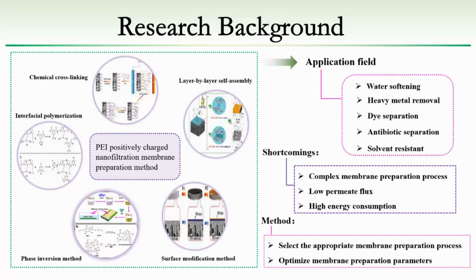However, these membranes still have some shortcomings that limit their application: complex membrane preparation process, low permeate flux, and high energy consumption. To solve these, selecting the appropriate membrane preparation process and optimizing membrane preparation parameters were effective methods.